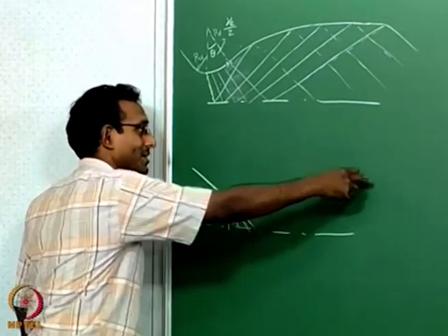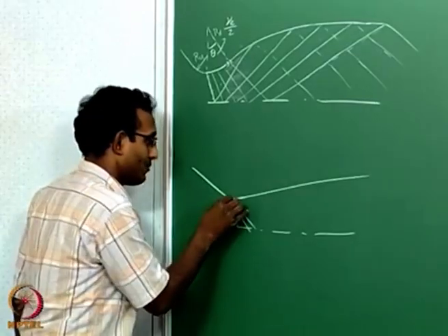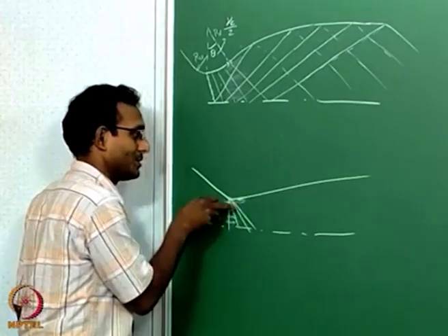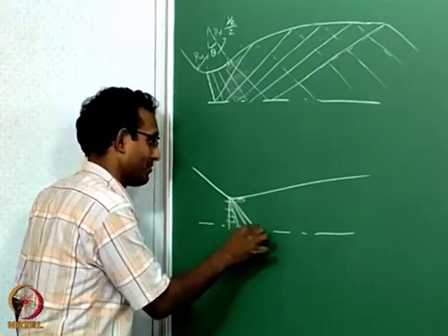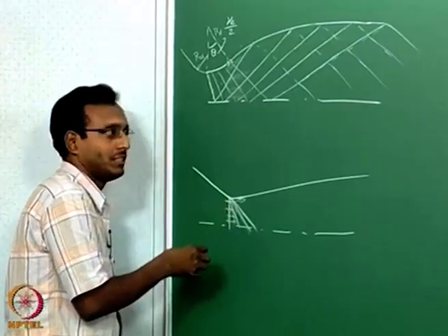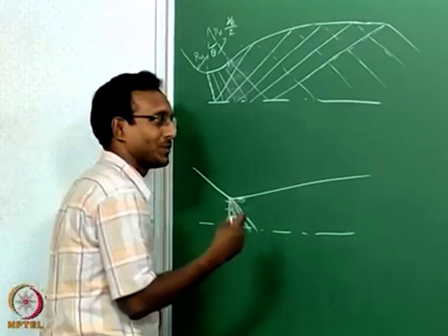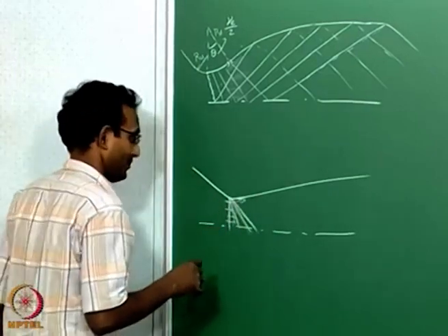It can be changing far away, but locally that is the angle, and I should be knowing that. And once I know that, now I can think about from Mach 1 to change to that angle, how much should I turn. So you just give that much of expansion fans here, and how many ever points you want on this you can give. Okay. Typically I will give 10 points, but I have done an example here with 20 points. Anyways, I can choose whatever point I want in here, okay.